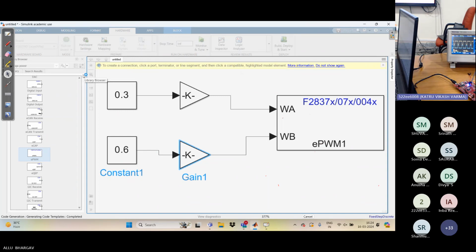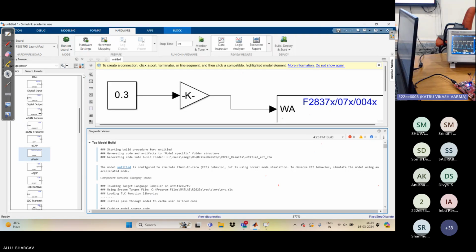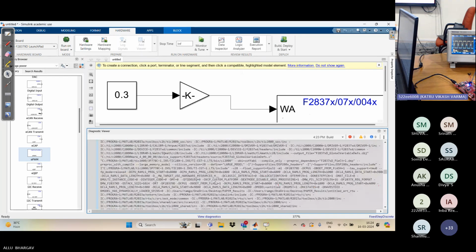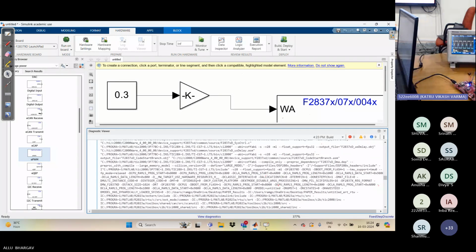EPWM-A will be, here we were using EPWM1. 1A will be 40 and 1B will be 39. And similarly, when you go for 2A, 2B, then it will be sequentially 40, 39, 38, 37. So output you can see in the camera, and I'm here displaying the output also.